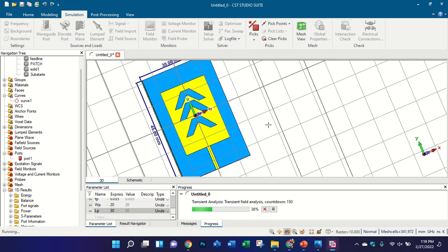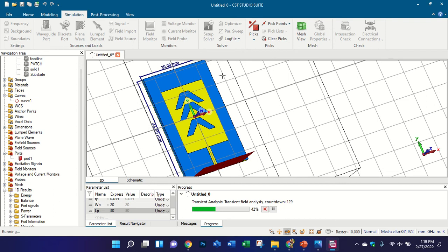If the size is smaller, it is hard to fabricate lumped elements like capacitors, resistors and inductors. That's why in most reconfigurable antennas we keep the size like this, or maybe smaller, but we do not use it in millimeter wave or in sizes less than 5 by 5 millimeters. Okay, thank you.